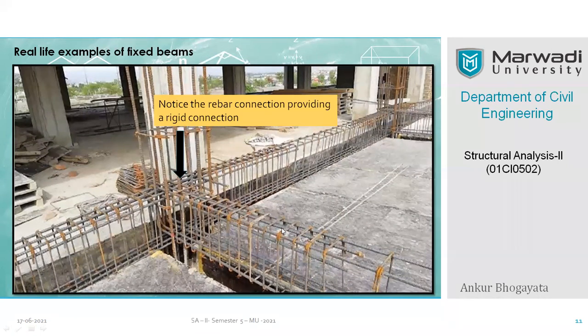This bar starts here and reaches over here, and it is bent over there on the main reinforcement of this other beam. It is also rigidly tied and connected by means of wires with the reinforcing bars of this column. You can see there is an upliftment, a bending of this bar.